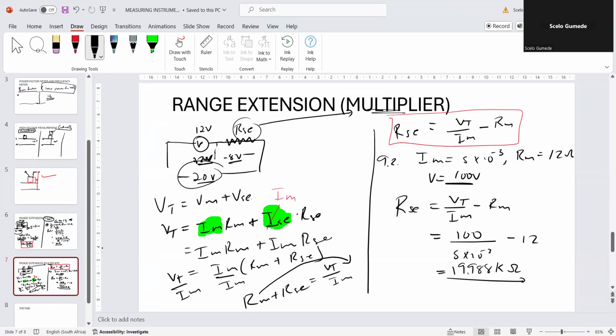All right. Excuse me. Basically, this is what I had prepared for you. Then the theory there, please go through the theory, whereby we are talking about digital measuring instruments, because the ones we've been doing were all analog. That's why we're speaking of deflection. Now, you need to know how to use a digital instrument meter. You need to know how to use it as an ammeter, voltmeter, and an ohm meter. Which points must it be connected at? You need to know for the care and maintenance, it must always be clean. You must also look at the advantages of using digital over analog, and answer those questions on 10.2.